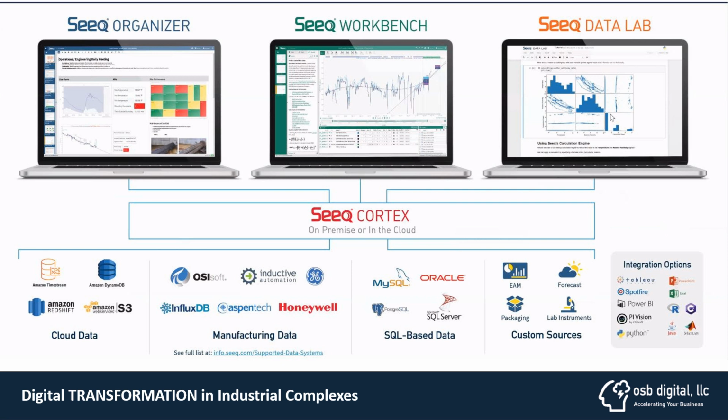For this, we need to have the right software, so we start looking at this SEEQ Cortex that collects all the data from the different historians, from your lab data, from your mine data, and that gets organized without touching the original resolution, and we transform that data into information using Workbench, where we can document exactly what was done for every unit and how you were transforming, calculating the first derivative, second derivative, putting the right filters.